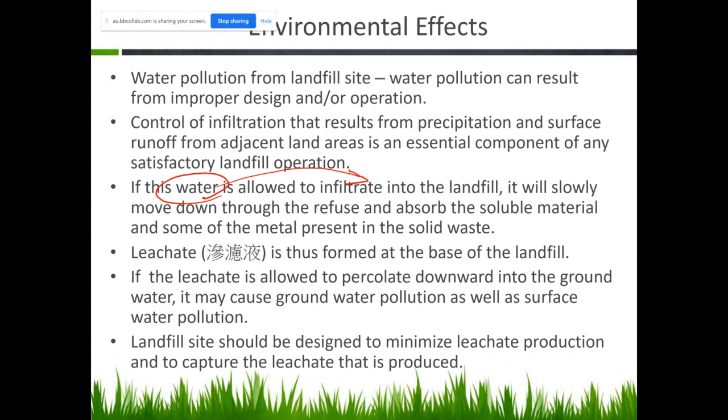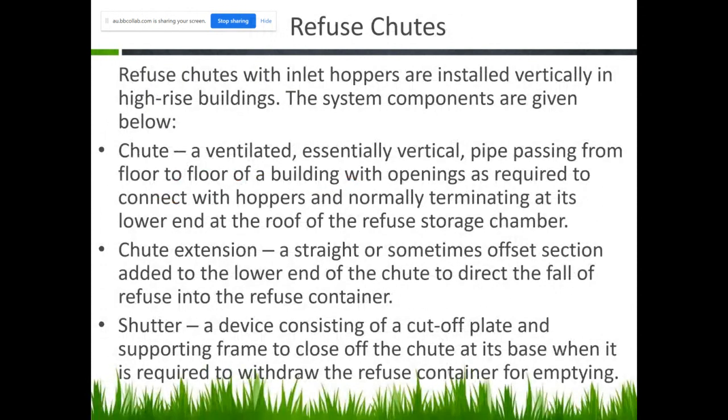This is one of the problems for the underground water. If you collect some of the underground water, it may be contaminated by the discharge of the landfill. And physically, the landfill will be settled. It may be required to reserve about 5 to 10 years to let it settle. So this is a lot of problems.